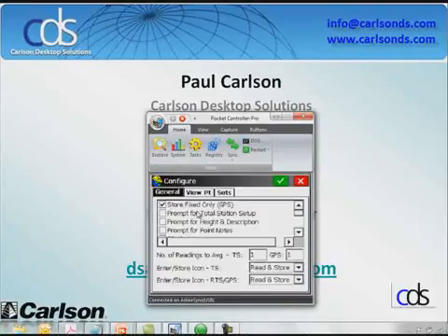Okay, I'm going to go into the configure and I'm going to turn a setting on or make sure I have a couple of settings on. Number 1, the store fixed only. This is an absolute must. I've taken a couple calls over the years from somebody that said, hey, my guy shot these property corners and they're not right. Or they shot these manholes and they're not right at all. They're in the wrong spot. It's all wrong. And what happened is somebody came in here and told it to, hey, I don't care if the point's fixed or not. Let's store it. Now, it does warn me. It does say, hey, this is not fixed. You want to do this. But I recommend, you know what, that should be turned on.